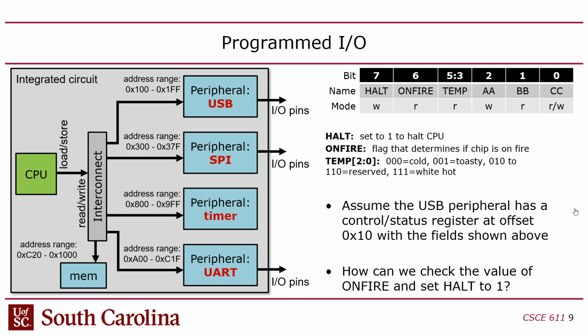Actually, it has it for everything if you go to the ESP32 Espressif library, but not if you're using strictly the Arduino. Anyway, there is software that creates a hardware abstraction: functions that you can call as opposed to having to do bit twiddling. But for the first few labs, we have you do the bit twiddling just so you understand how it works. So when you go to work for Apple and they introduce a new neural processor unit, you have to write the Linux driver for that, and you would have to do bit twiddling for that, right? Does that make sense?